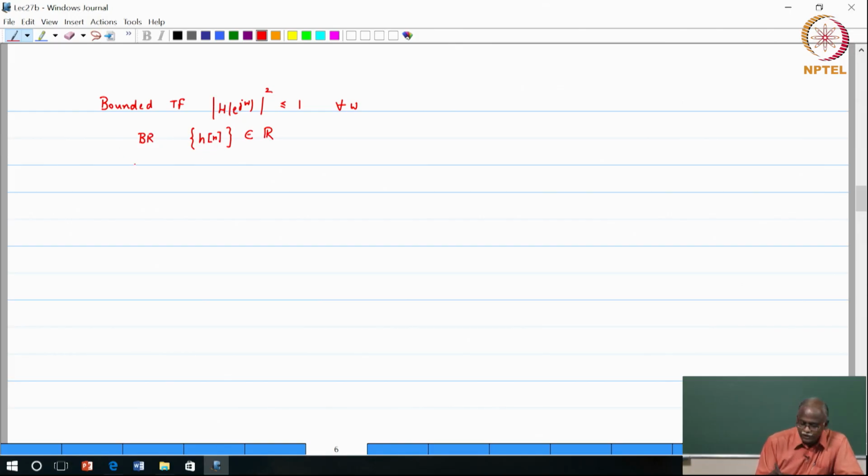And of course, you can have the lossless property, which is the same as energy preserving between the input and the output, and the all pass is one of those classes of functions, and therefore, if you have LBR, that basically points to an all pass with real coefficients. Okay. That is an important observation.